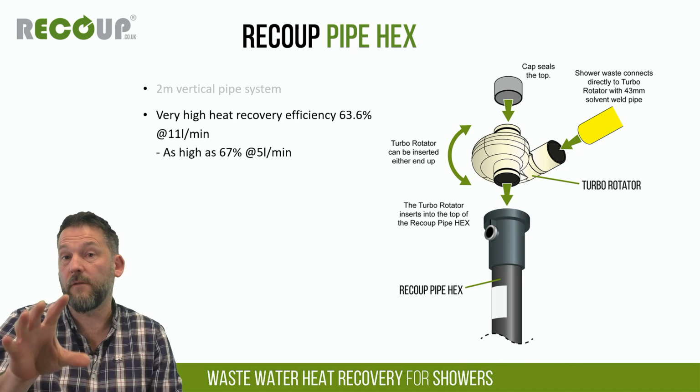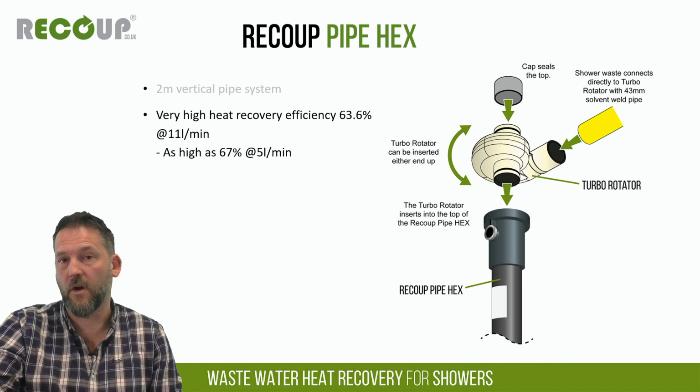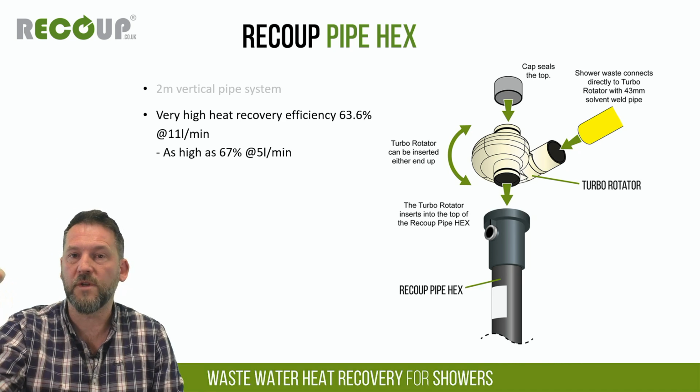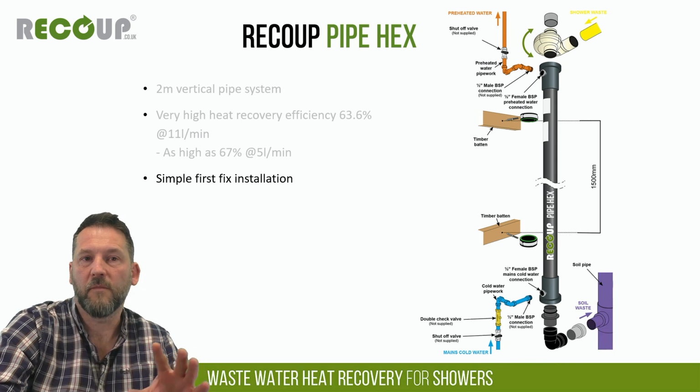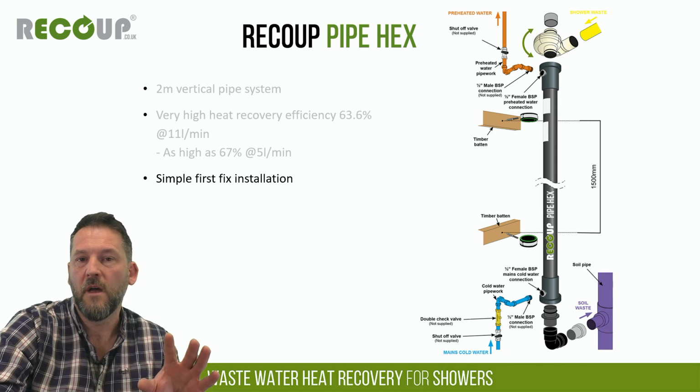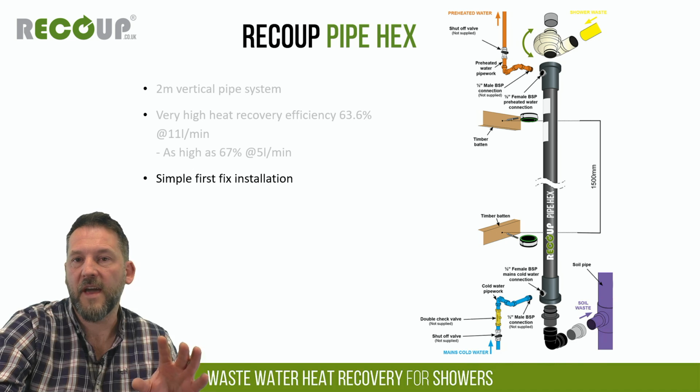That heat energy from the warm waste then imparts to the copper heat exchanger, and then cold water main comes around the outside. So we just highlight that here, pretty much as we showed earlier. Cold water main coming in, goes around the outside of the exchanger pipe, comes out preheated.